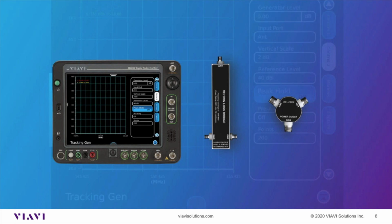If you find that the VSWR is really good 5 megahertz away, then you may determine that it's just a matter of the antenna tuning being wrong. I've talked to people who do installations, and one of the nice things about using the tracking generator is that if you have a new install, you can go out there, sweep the antenna, and verify it's on frequency without hooking up your transmitter and possibly endangering it. Say your install team came in and put a VHF antenna up instead of a UHF antenna. So it gives you a more complete picture of the health of the system.